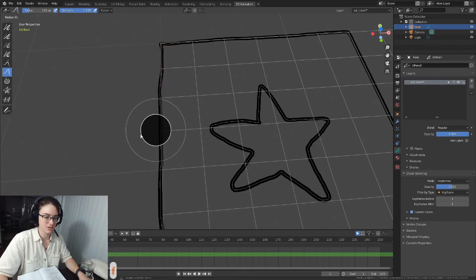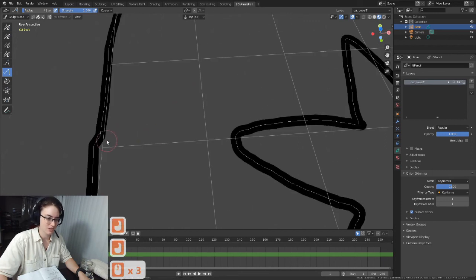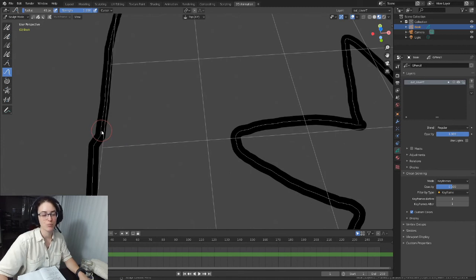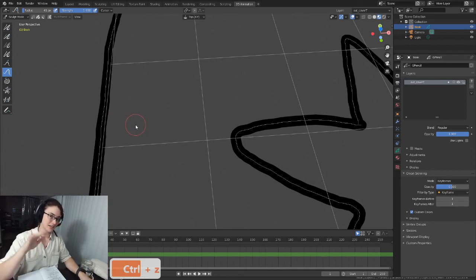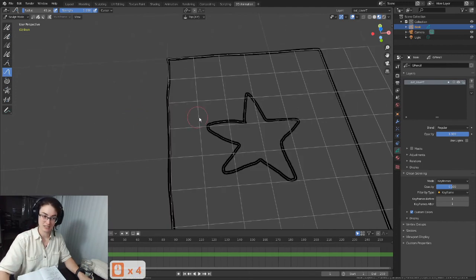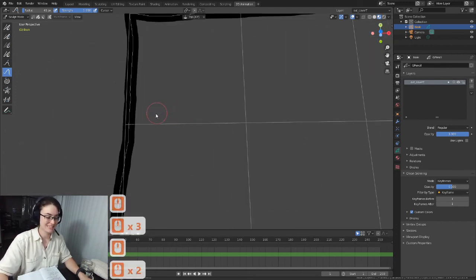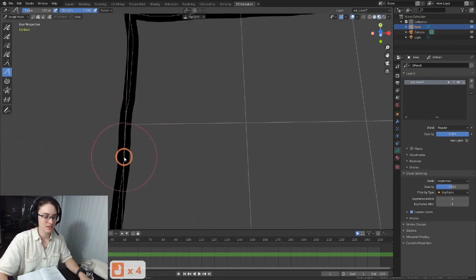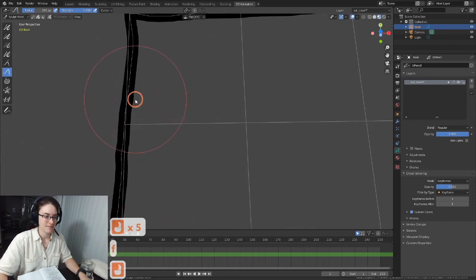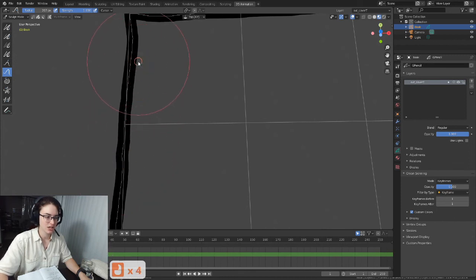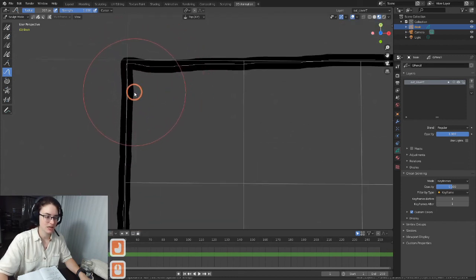And this is where you can see that if I pull stuff, it gives us sharp points. That's just where those points are that make up the line. If you do need more points to make it smoother, you can go into edit mode, do the selection, then right click and hit subdivide. So, hot tip. But otherwise we're just going to hit F, scale this, and smush stuff around to try to make it a little bit better of a line.